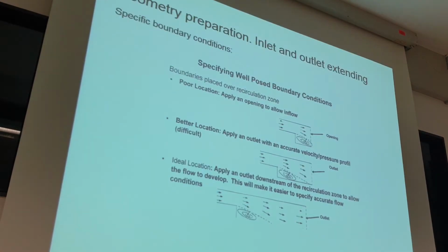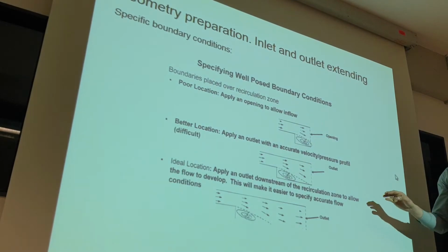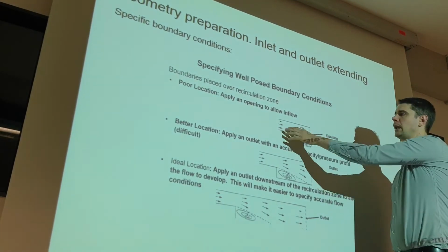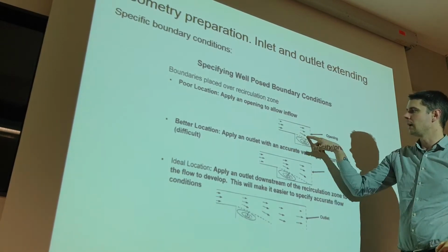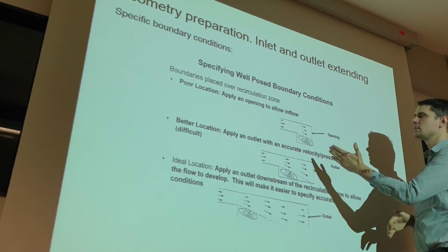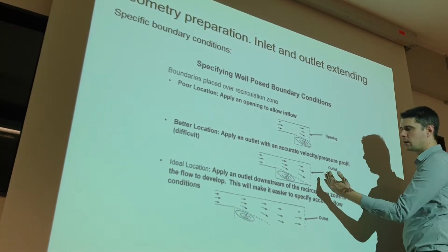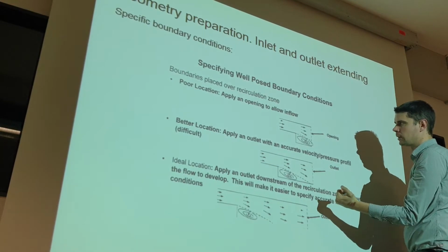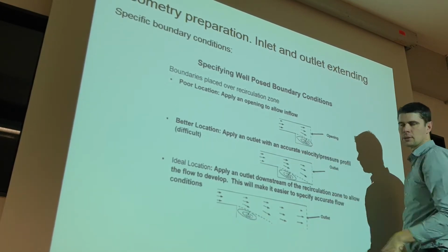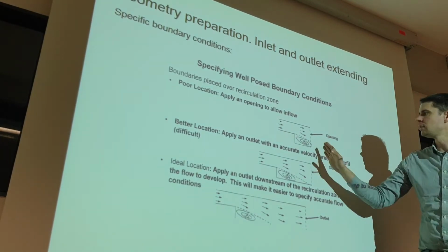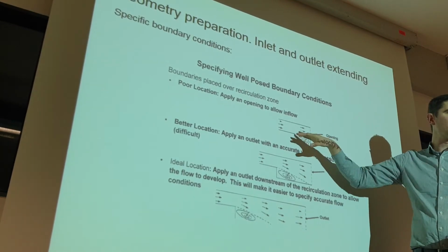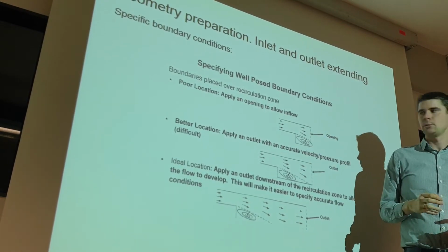The problem is this problem, yes? Normally, I have turbulence, and then I have here the outlet with turbulence, yes? So what does my boundary condition outlet mean, for example? It means everything goes out, yes? If I have turbulence here, then the program will say, no, here is out, so out. And now flow goes back into my simulation, yes?